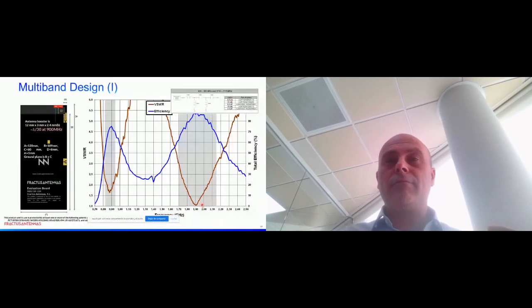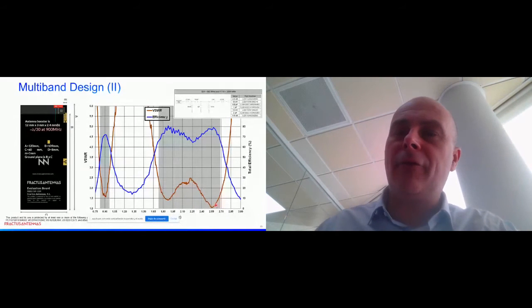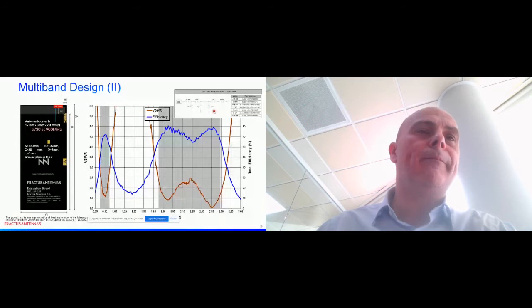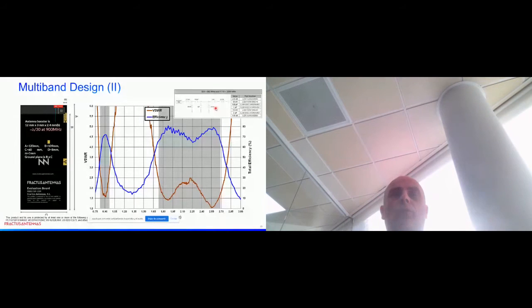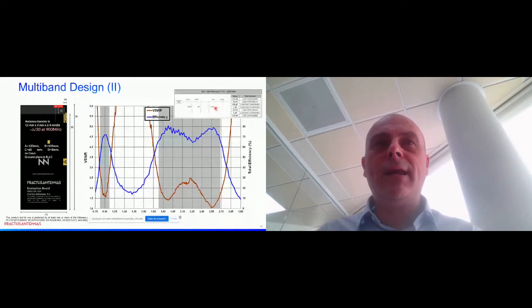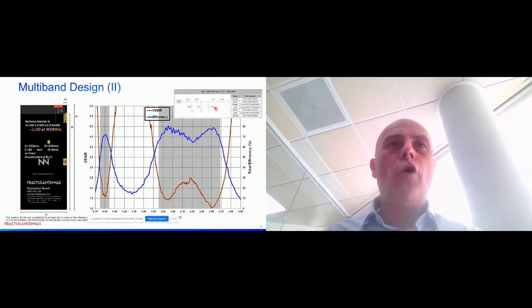And even more challenging, you can expand the bandwidth, reaching most of the LTE bands, by again changing the matching network. You see, everything is the same. The PCB was the same, the antenna booster is the same, and we only customize the matching network. As you can see, antenna booster in combination with a matching network and the ground plane are the essential parts of a virtual antenna architecture.